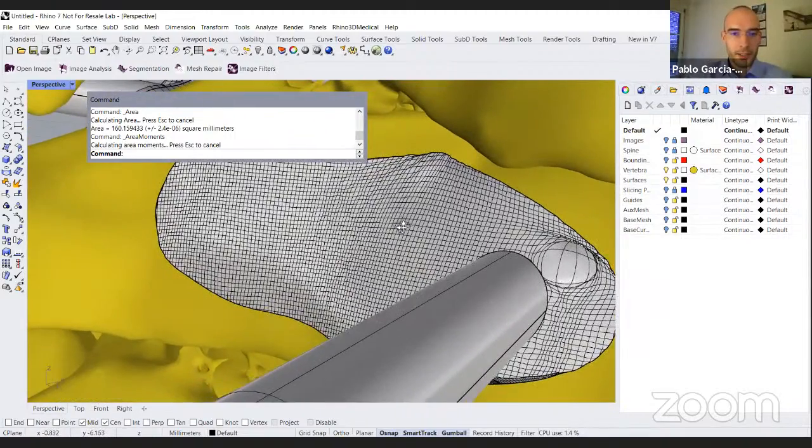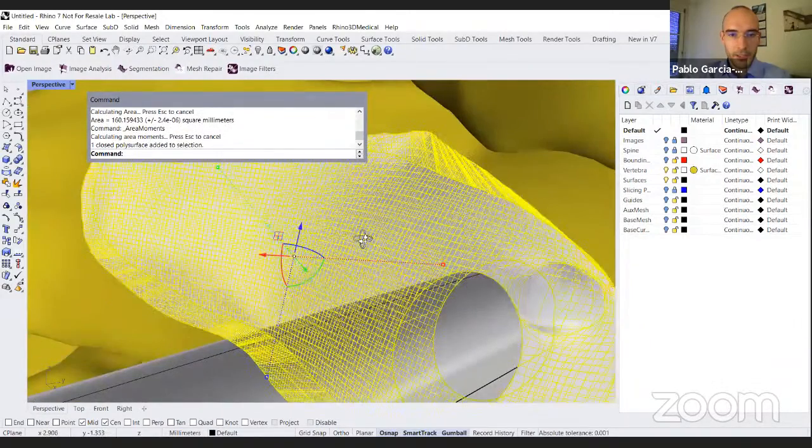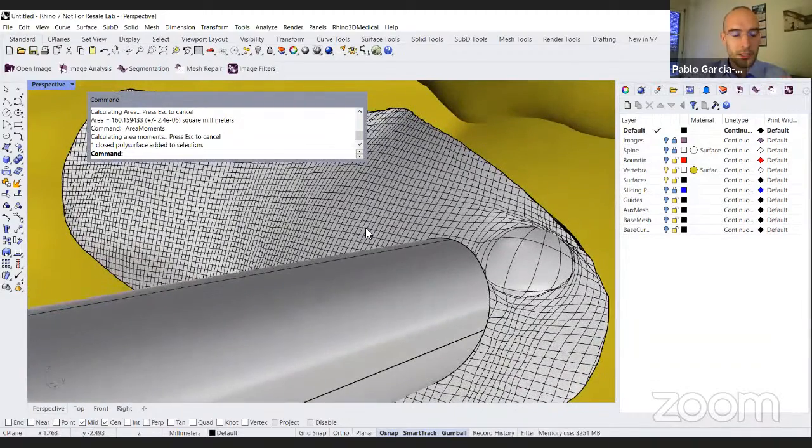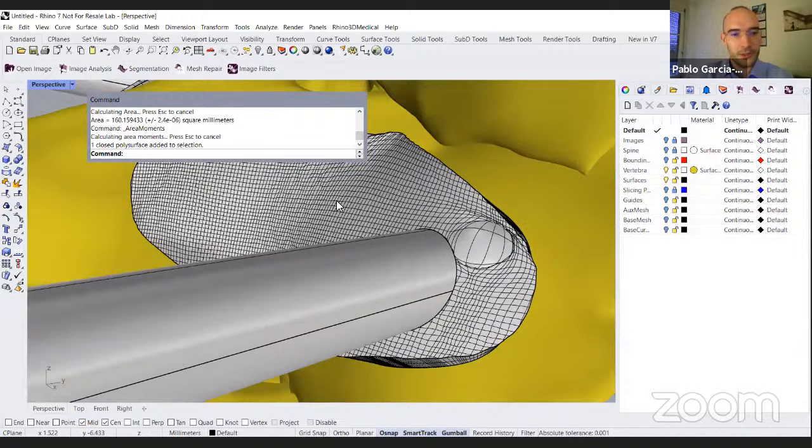As you see here, the drape shape is too complex, too dense, and that's something the McNeel guys could work out, how to improve. But it's a very helpful function. For much more advanced drape functionality, you could try Kangaroo, a physics engine included in Grasshopper. It's another story, but there you can simulate a drape with much more precision.